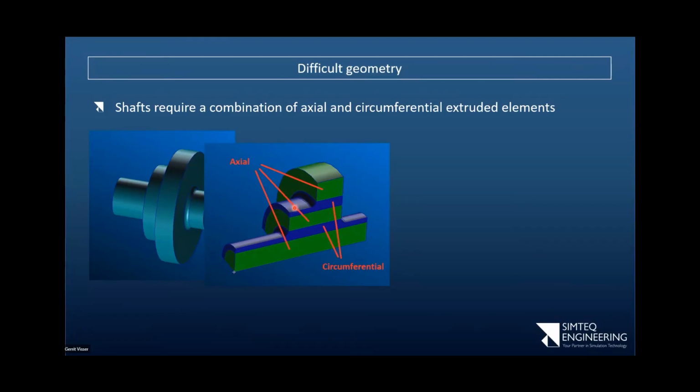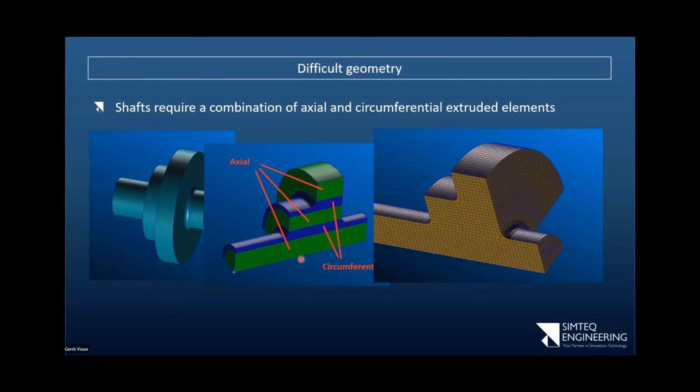On these though, it's not possible to mesh this and extrude in that direction. There are a couple of methods that will allow something like that. So if this was a straight section, I could in theory have had an element at an angle like that. You usually get pretty bad meshes if you try and force something like this, but it is possible to do that. Okay, so instead, if I mesh these blue faces on this face and extrude it in the radial, or sorry, in the theta direction, the circumferential direction, I end up with a mesh looking something like this.